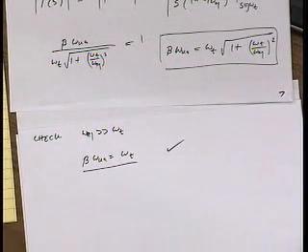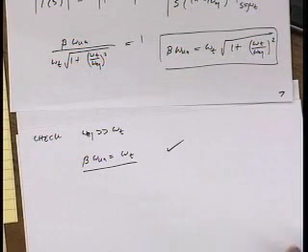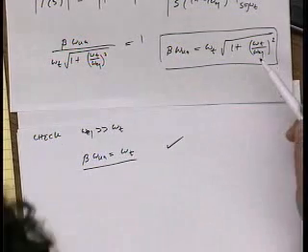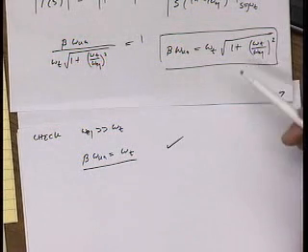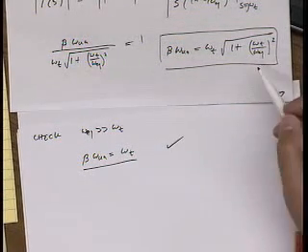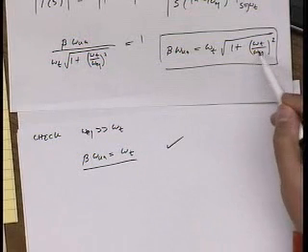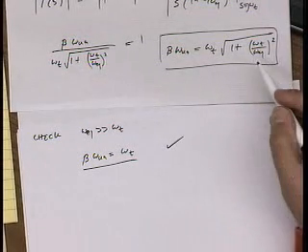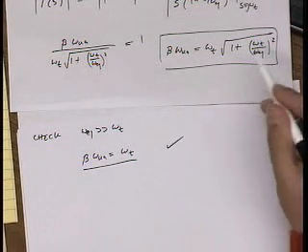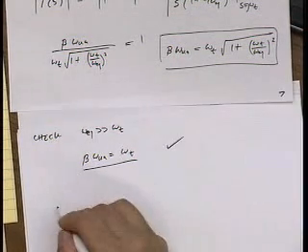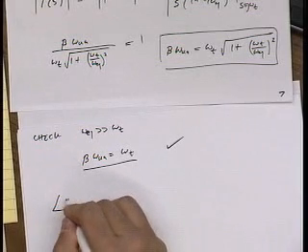Okay? So now the question arises on how do you choose the location of omega equivalent? Because that might be under your control. By properly biasing your amplifier, you can move this pole around, or if you're doing some kind of pole splitting, how high up does this second pole need to go? And to answer that question, of course, we check our phase margin.